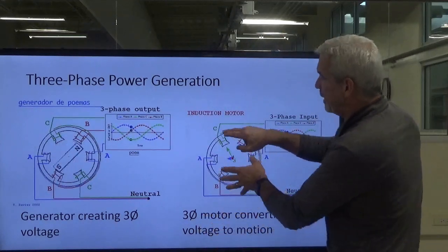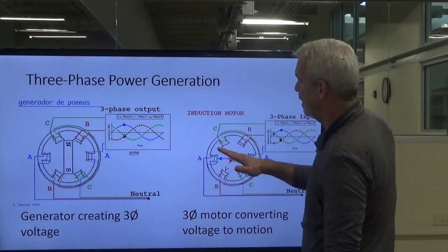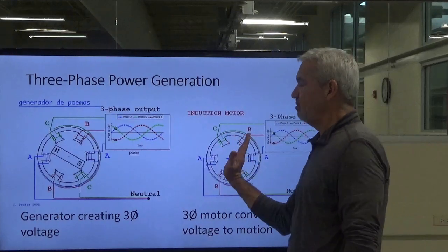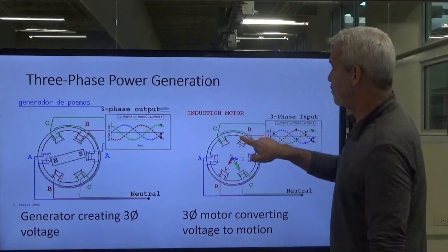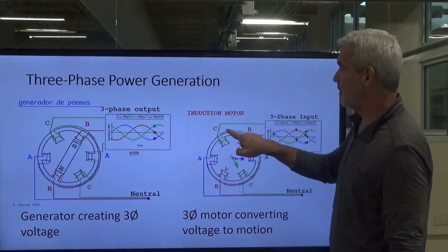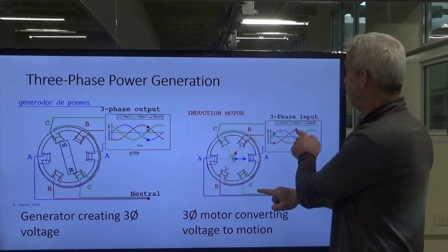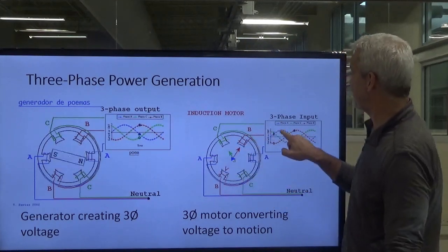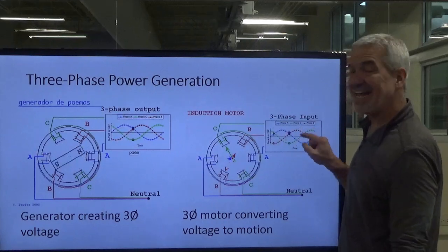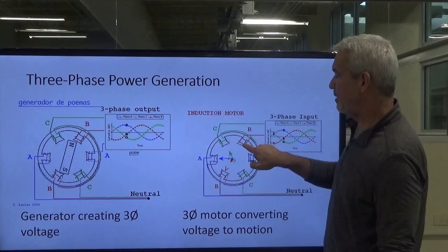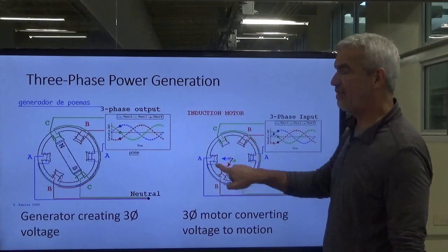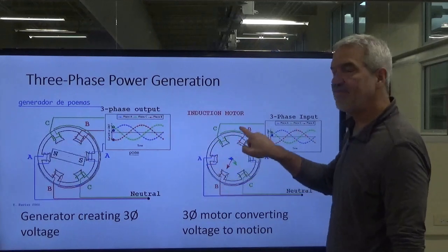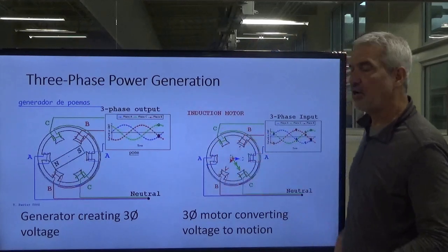We're connecting it to the coils, and they become magnetized, and that rotor wants to chase the strongest magnetic field. Well, the strongest magnetic field is constantly changing. It's changing based on whichever phase has the peak voltage at that particular instant. So it never is satisfied with one. It's chasing them all around, okay? It's just going from one phase to the next, one phase to the next, and goes around and around the circle, okay?